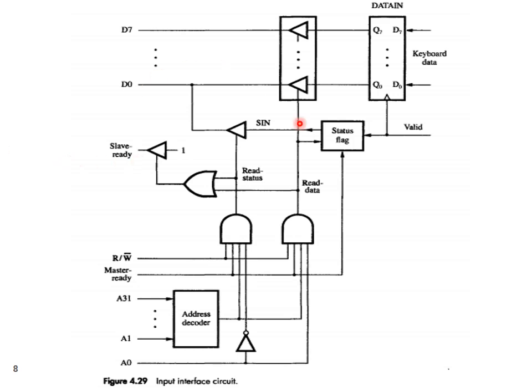So this is how this circuit of the input interface works. Whether I am reading a data value or reading the status value, both are initiated by using some 3-state drivers, and similarly the slave ready signal is also sent to the processor through a three-state driver.